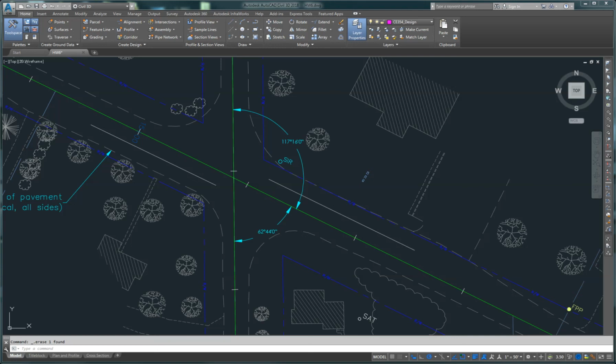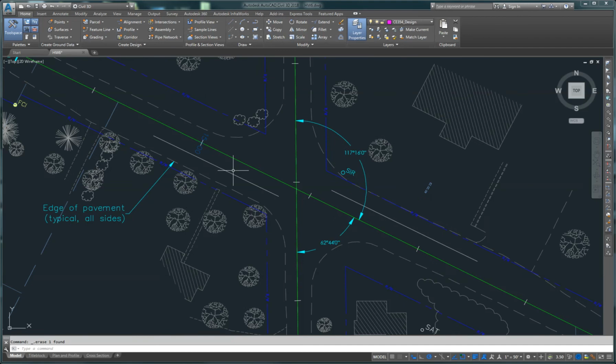Hi, for homework 6, we are going to do some work in AutoCAD and draw out our radiuses on a drawing file. So if you download the homework6.dwg file from Blackboard and save it to your H drive, you should see this when it finally comes up. There'll be a couple of screens saying that you're missing a shape file or missing some other files. Just click ignore on both of those alert screens that come up, and don't worry about those. You should get into here.